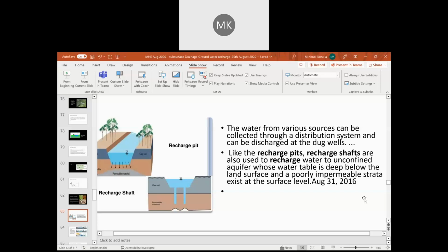And as I mentioned, we have to decide the pressure which is coming on the aggregate drain or the drainage geocomposite. Okay. So there are calculation steps. The IRC 42 will give the calculation steps for the conventional drain, and IRC SP 59 will give them for the drainage geocomposite. Both these documents are getting amended now. So within 2 to 3 years, you will get a better methodology of adopting the drainage geocomposite as well as the aggregate drain. Okay.